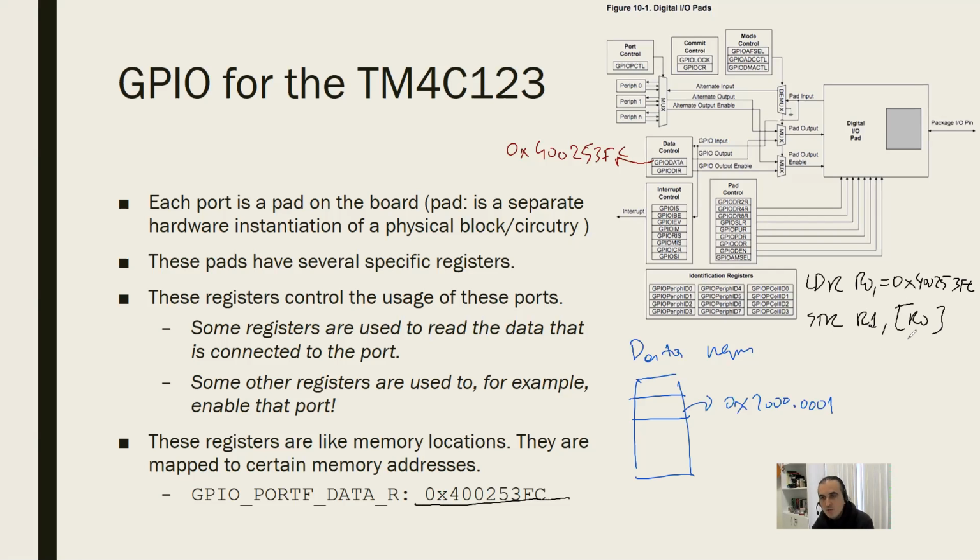Previously, you knew that this was to access the memory, right? I get the value inside R1, the scratch register, and write it to a memory location. Which memory location? The one this pointer points to. Because this value is not mapped to the data memory, it is mapped to this register. When you do this, because the pointer points to here, you are not writing to the memory, you're writing to this register.